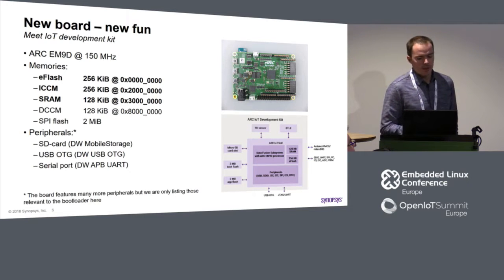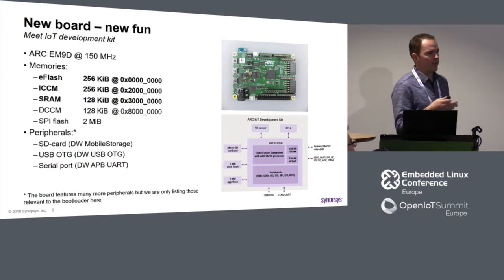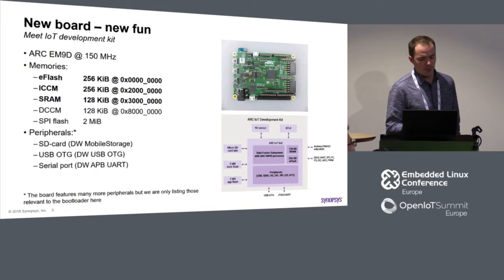That basically meant we needed a bootloader which may support these peripherals, and may support a FAT partition, which is usually used by developers on Windows machines. And here I think U-Boot is quite a good match.